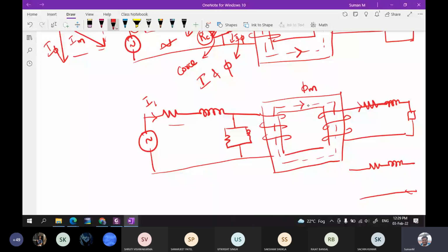So even when the current flowing in the secondary is zero, the current flowing in the primary will not be equal to zero. Okay, why? Because even if the transformer is not loaded, that means I is equal to zero on the secondary side in the open circuit, some current will still be flowing on the primary side. That current is flowing to magnetize the transformer. So for the magnetization part and the core loss, we'll have XM, and we'll call this XSC and this RSC. So there is some current, that is the magnetization current.